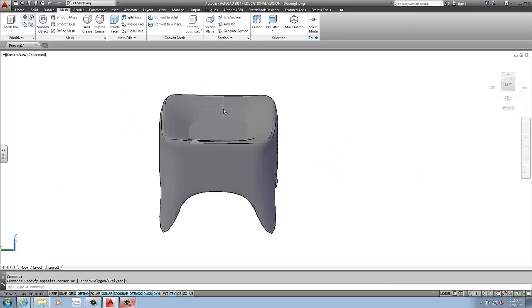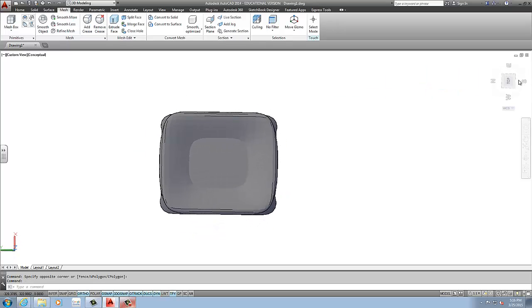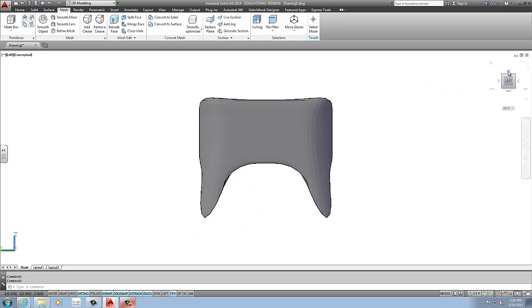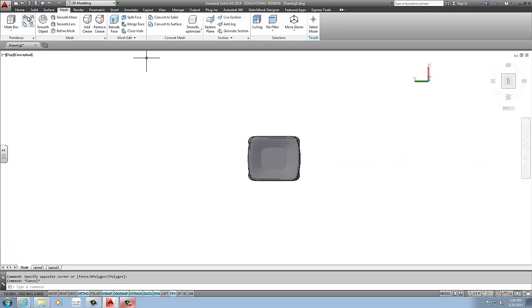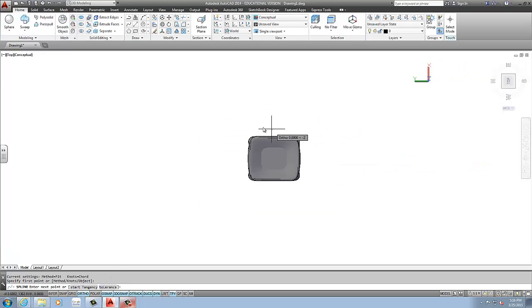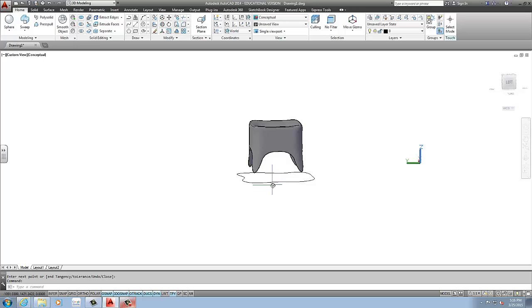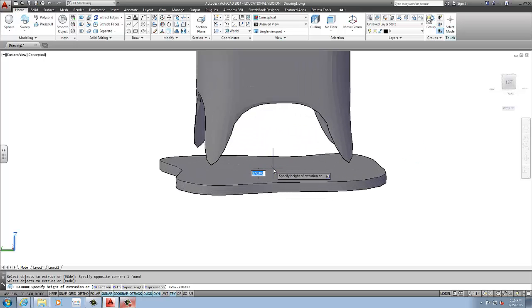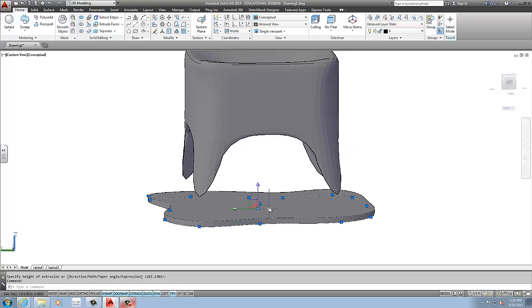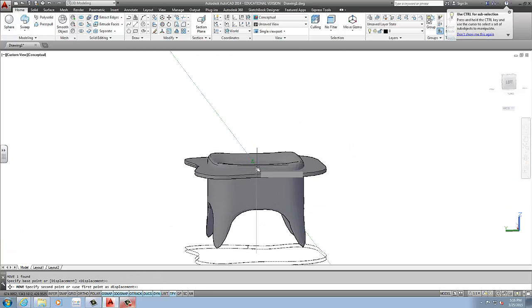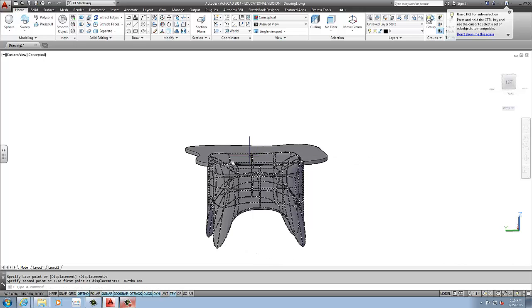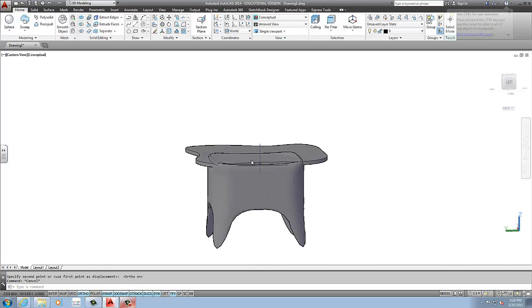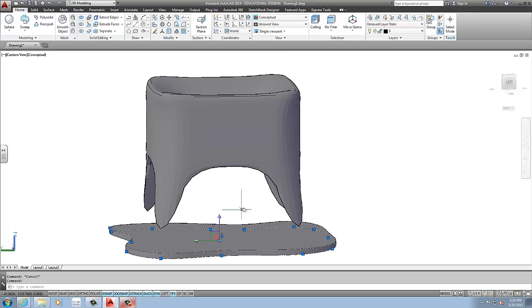Okay, so from that point we created what we call the table. Let's go back to top view and create a spline coming over an overall design shape of the part. And of course it's going to be oversized. I'm going to extrude it out, giving it some form of thickness. And finally, move it up. Oops, I think I snapped onto something, creating a problem, so I'll do this one, move it up.